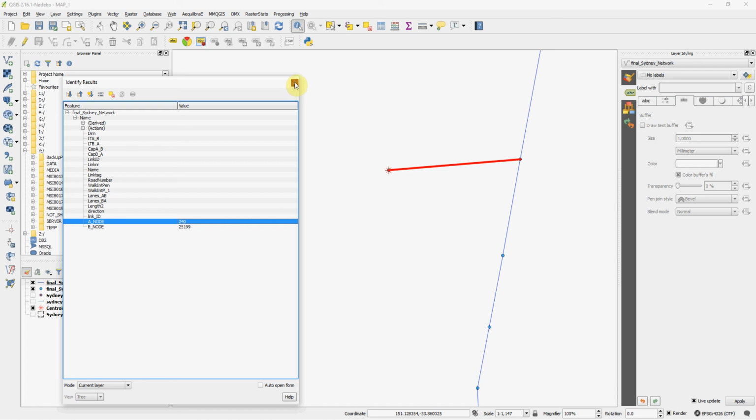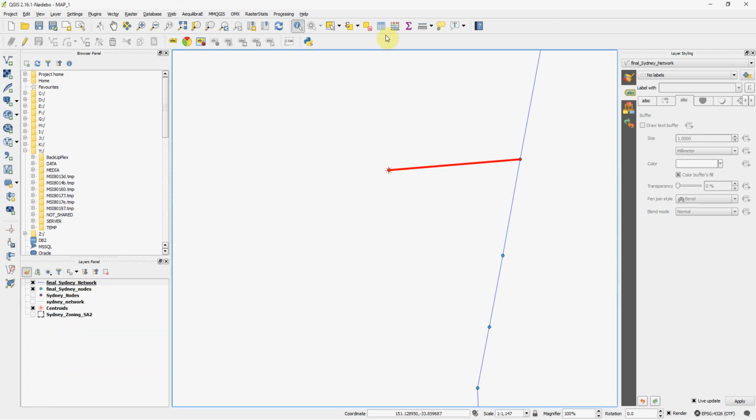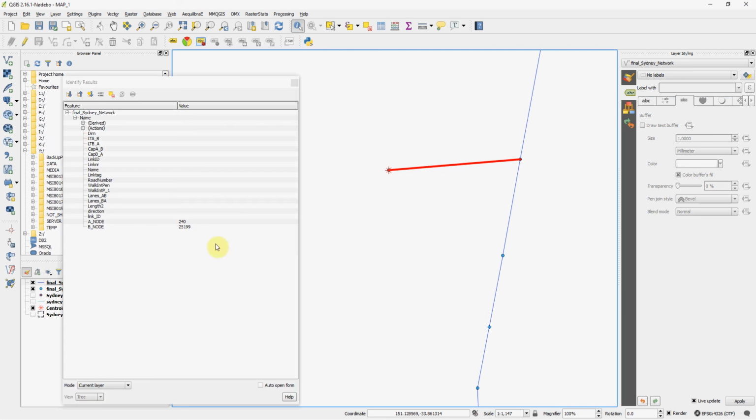Just one thing you need to pay attention to here: link IDs are not filled, neither are all the other fields. So you're going to need direction, link ID, and some field for length at a minimum to use AequilibraE to compute paths. If you're going that direction, after you finish adding centroid connectors, you have to go through all the fields you're going to use in the graph and fill them out properly. So I hope this was helpful.